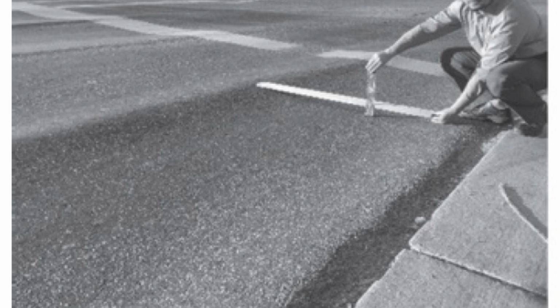The hot mix asphalt, HMA, is displaced downward, laterally, and then upward to form ridges on either side of the wheel paths. Unstable asphalt layer or too little air void leads to shear rutting. Treatments: small amount of rutting, less than 1/3 in.